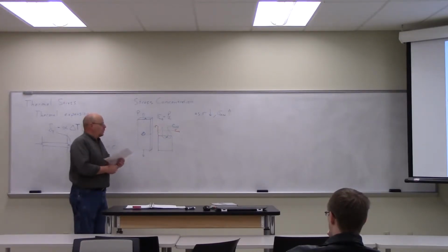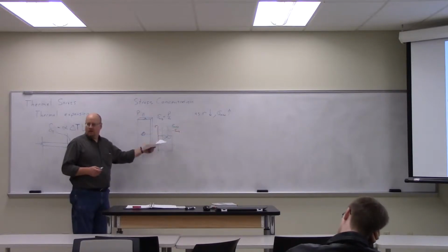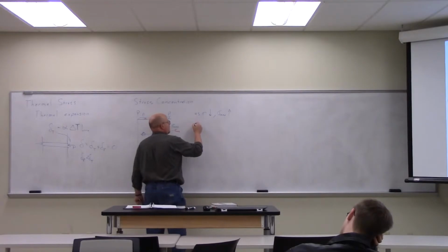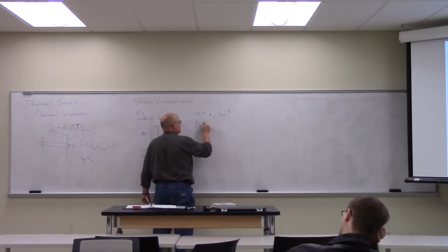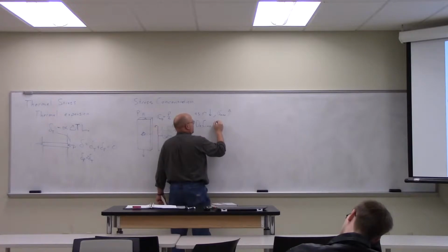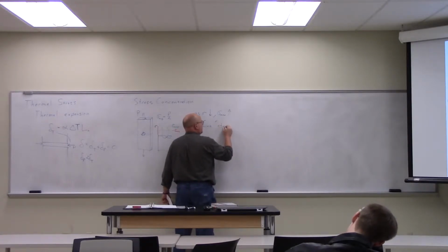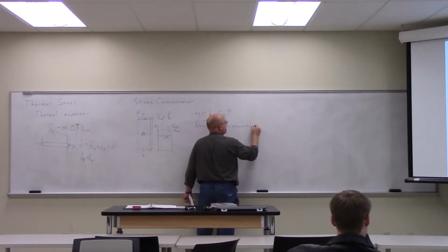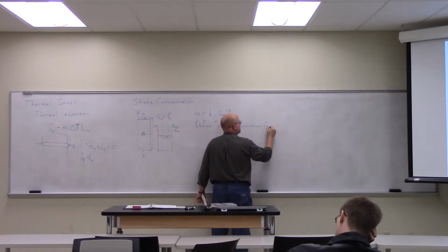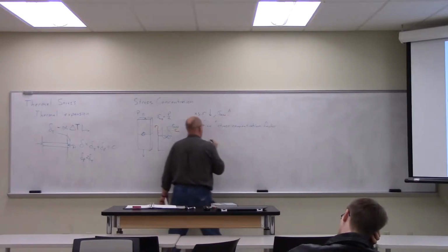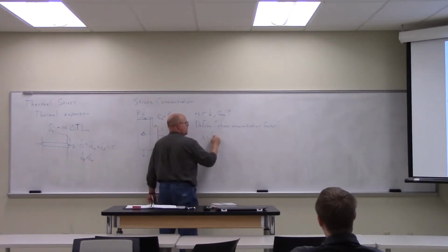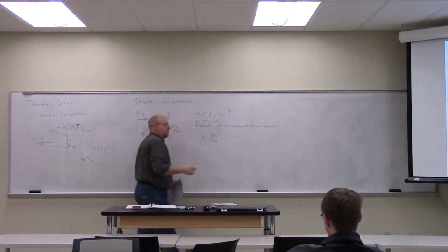Okay. So rather than try to dig into the math behind this, because it's not nice, easy, clean, exact math, we instead, for the purposes of this class anyway, are just going to define a stress concentration factor. Give it a capital K, and it is just the ratio of that maximum stress to the average applied stress.